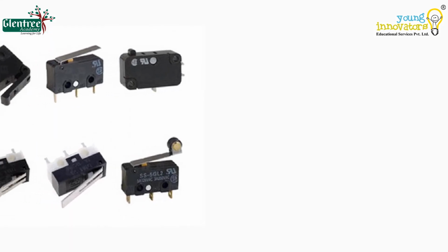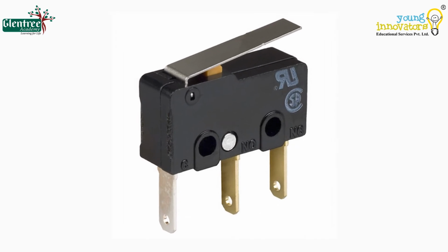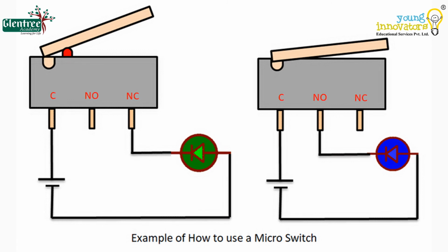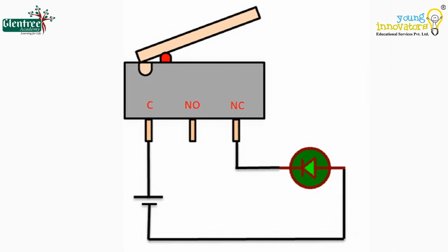We shall look at a microswitch now. Microswitches have either a small push button or a lever in order to start the switch. They require very little physical force in order to operate and are ideal for small scale projects or applications. Here is the circuit connection showing the working of a microswitch when the lever is unpressed and when it is pressed. The input is given to the common terminal. The switch is in closed position.